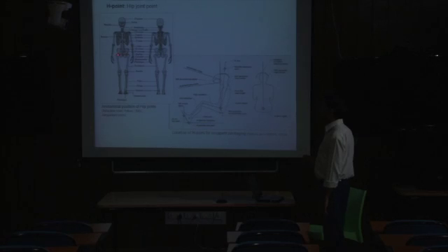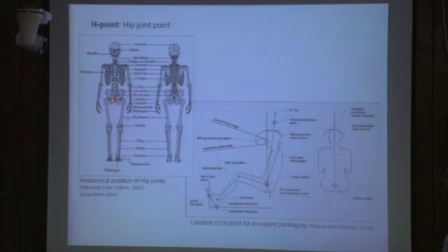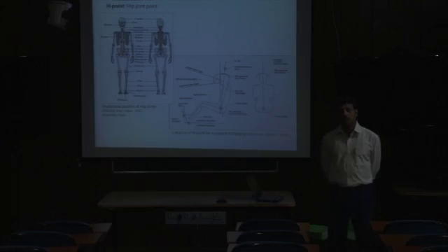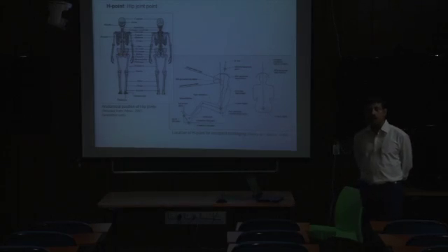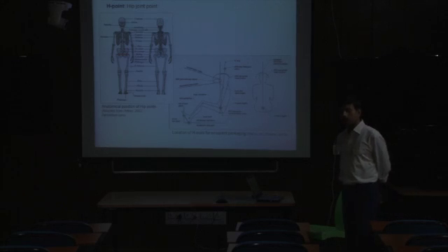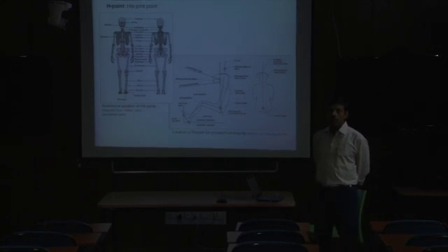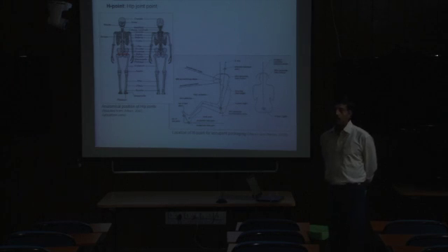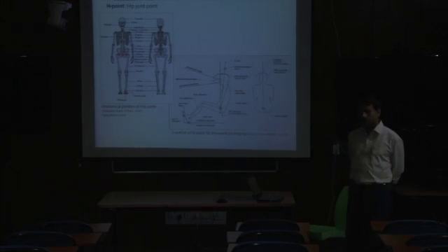This hip joint, if we connect with an imaginary line, this line does not exist, it is an imaginary line. The middle point of that imaginary line is known as the hip joint point or H point. Based on that, the H point is very important for us, because in a sitting workstation, the digital human model is positioned on the seat depending on the H point location.